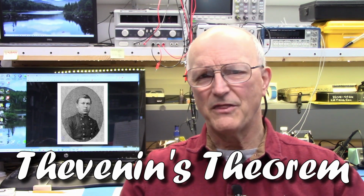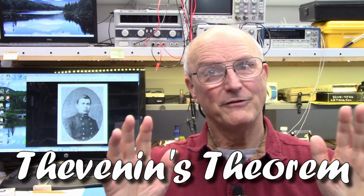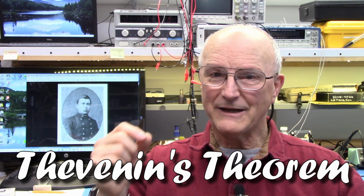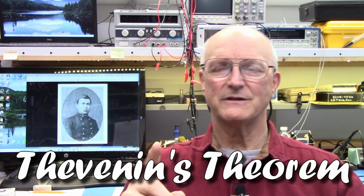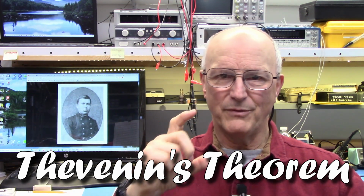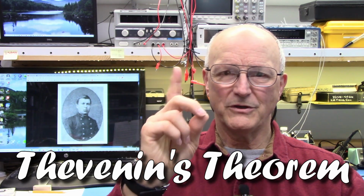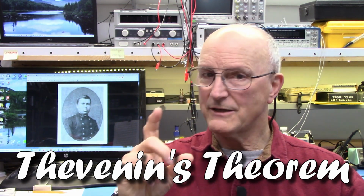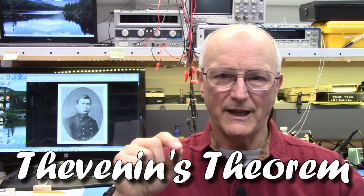So what does Thevenin's theorem tell us? Well, hang on, this is going to be a little confusing, but here's what it says. Any linear electrical network containing only voltage sources, current sources, and resistances can be replaced at terminals A and B by an equivalent combination of a single voltage source V sub TH in series with an equivalent resistance R sub TH.